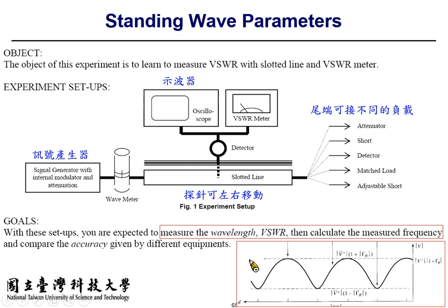So what you need to do is record the maximum of the sinusoidal signal and put them on this plot at different positions, so that you will end up with a maximum voltage variation plot like this. So if you only have an oscilloscope, you can still get this result, but it may take you a certain amount of time to complete this graph.